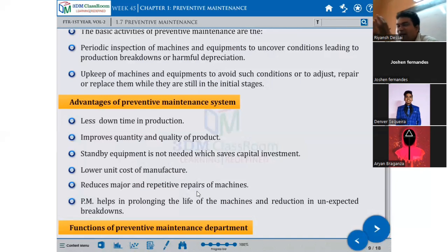So this fire hydrant system is a utility type. There is one pump running continuously without any operator. Suppose the pressure goes down, it starts, and when the pressure is restored it stops automatically. Similarly there is another pump and pipeline called the standby pump. If sometimes there is a breakdown, they start to run that pump.